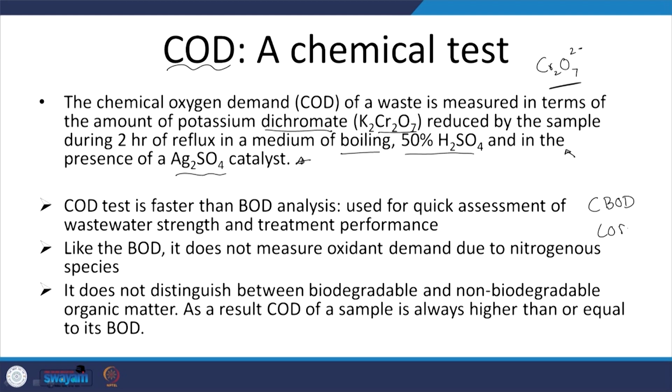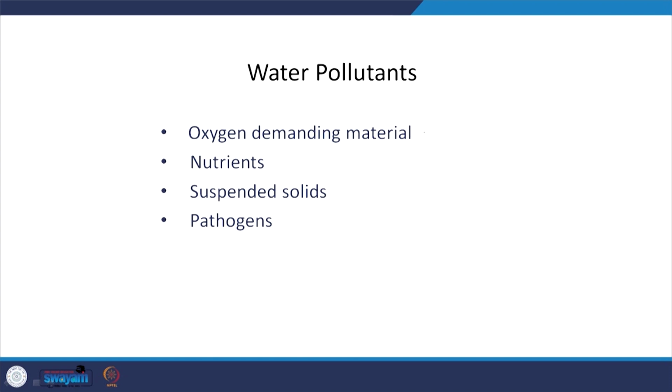Even the COD test will not oxidize or lead to oxidation of your ammonia. So, that is something to keep in mind though, right. So, we have spent considerable time on oxygen demanding material, but that is worthwhile because during water and wastewater treatment we are always concerned with oxygen demanding material.